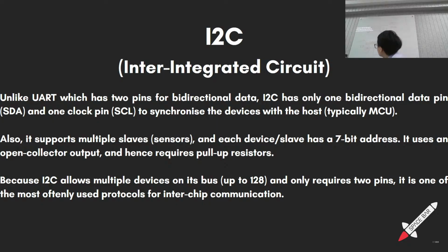A lot of the chips will have just some address, and you just deal with it. Sometimes you cannot use a chip because it has an address which conflicts with another address. It's quite rare because there are enough addresses, but it's difficult to totally fill the bus with all the devices.